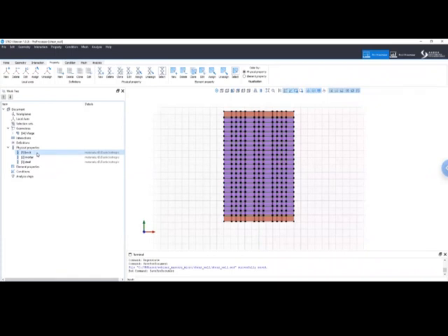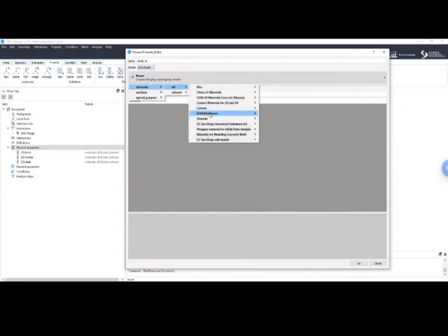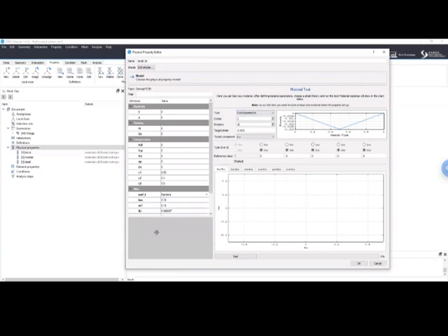Now we need to do a couple of steps. First of all, let's create the brick. In this model, brick and mortar should be 2D materials. Now, actually, the material that I'm going to show you is a three-dimensional one. So we need to transform it to 2D later on. So let me first create another material model, which is called brick 3D. And we are going to choose a material model under the ND material, the software's damage TC 3D. So I'm going to show you the parameters for this one.